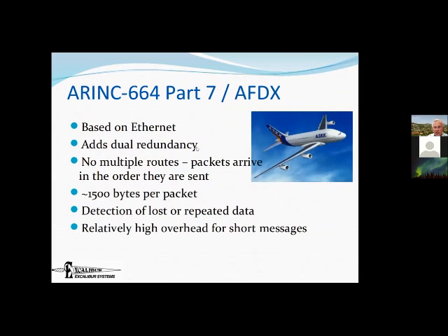And ARINC-664 AFDX, which is based on Ethernet, has yet another method of working, and that most people are familiar with from their offices: each individual computer that's attached to the internet is really first attached to a hub or a switch. And then that switch is in turn going to be, usually from your office, attached to the phone company or to a satellite dish.